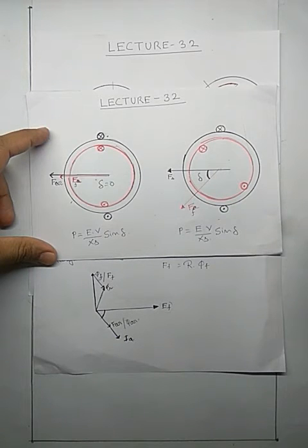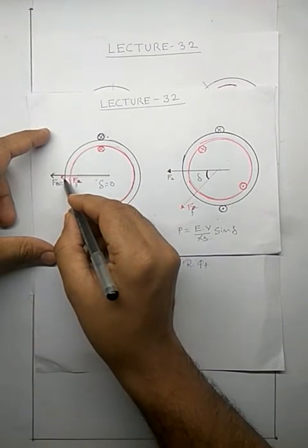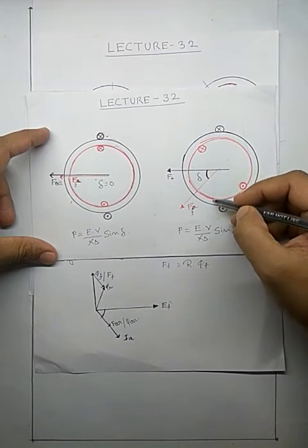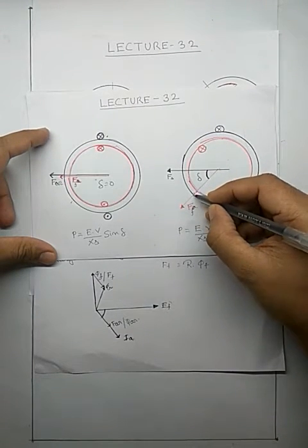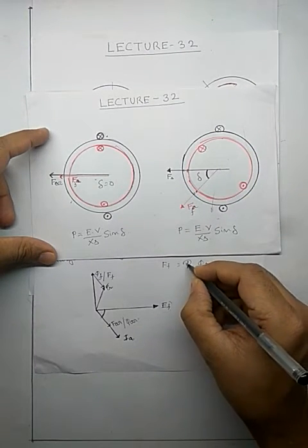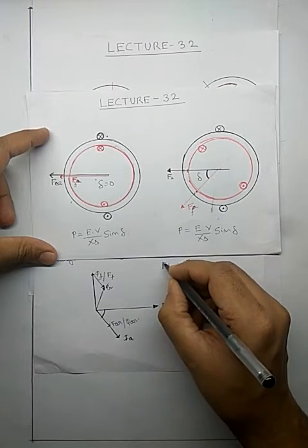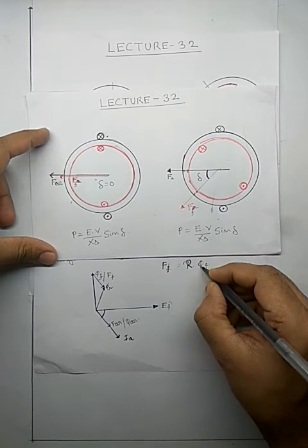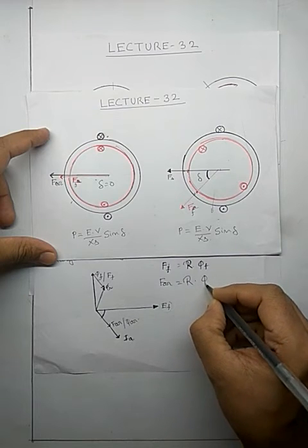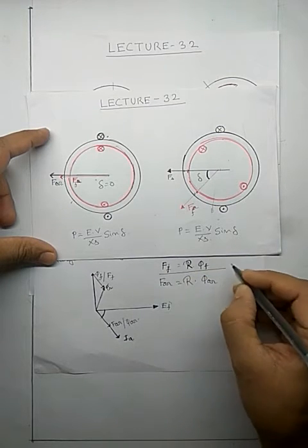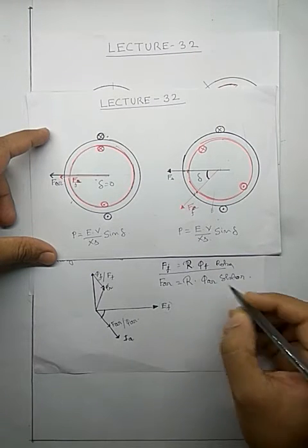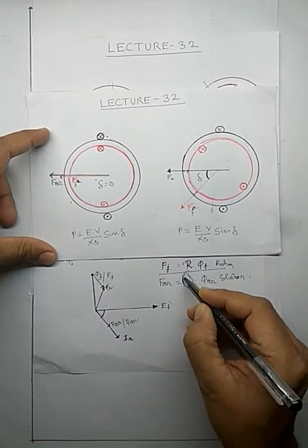Under what assumption have we drawn this? Whether my stator flux and rotor flux are here, or at this angle, or at some other angle, the air gap is constant. Since the air gap is constant, the reluctance that we have used to find the relation between phi f and Ff, or phi AR and FAR, for rotor and for stator, is constant.